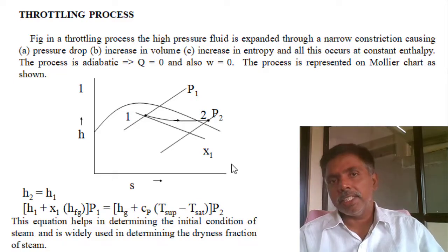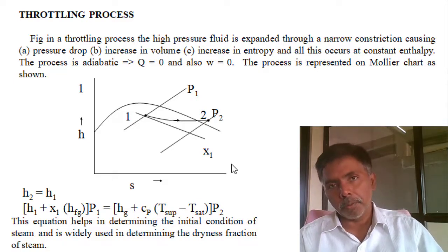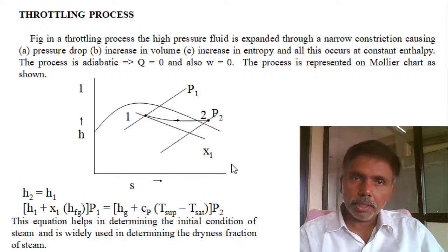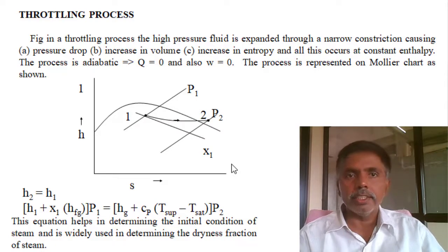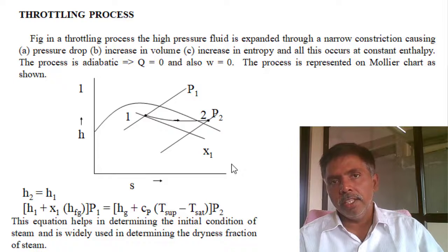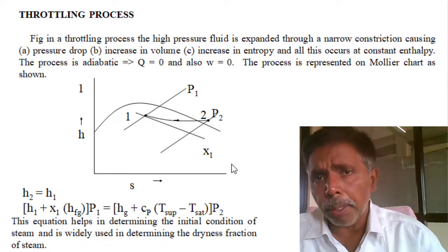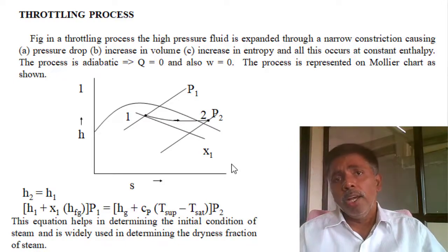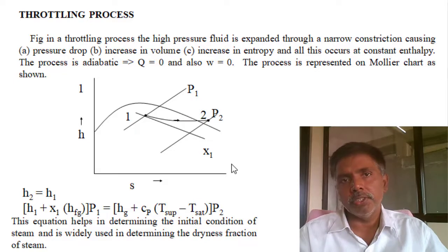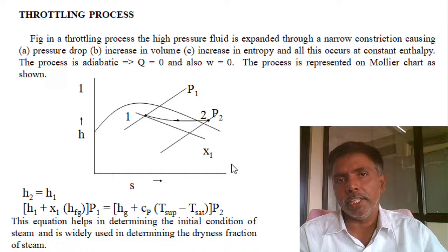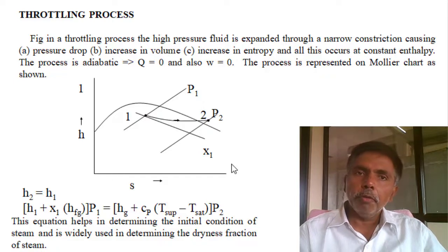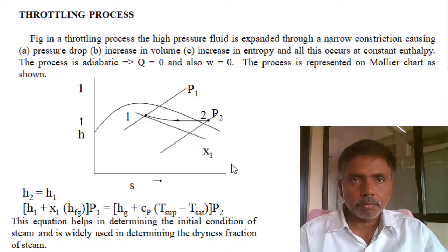And the second application is generally industrial, separate from refrigeration and air conditioning, in heat industries wherever heat is required, like the pulp and paper industry. At the turbine exit, generally wet steam is there, maybe dryness fraction 0.8, 0.9. We want superheated steam.